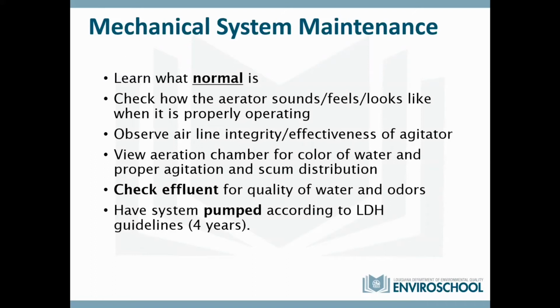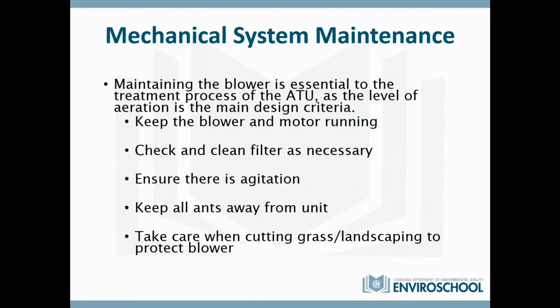And here's where it is. The Department of Health's guidelines say to have the system pumped out at least every 4 years. But again, that's a guideline. You may need to do it more than that, depending on your loading into your system.